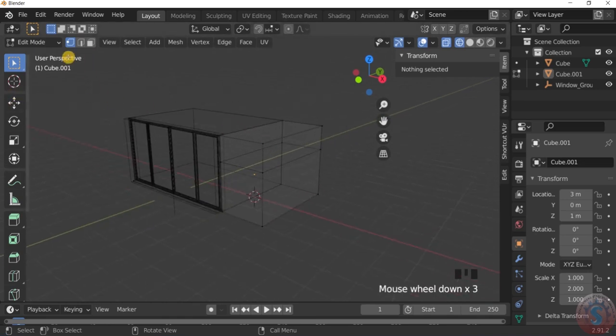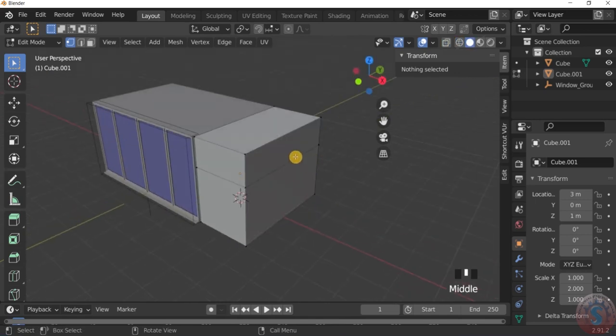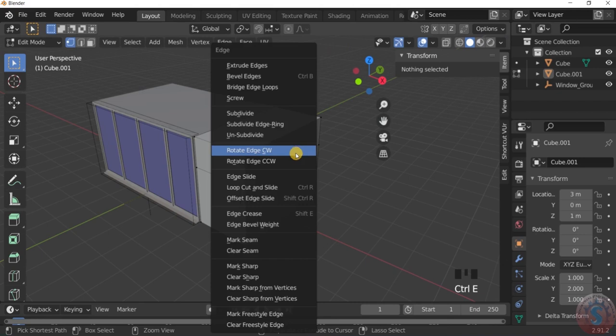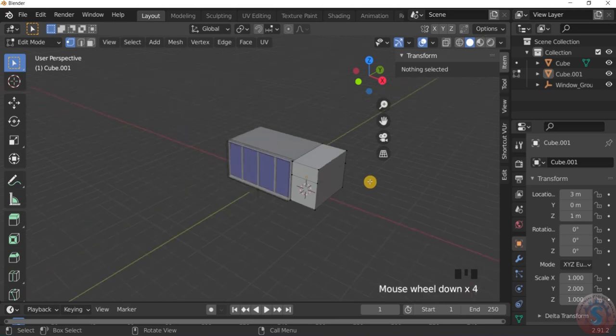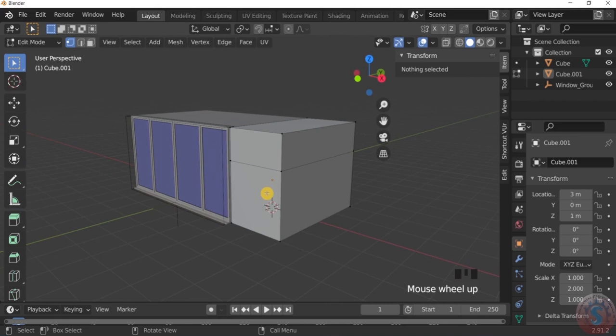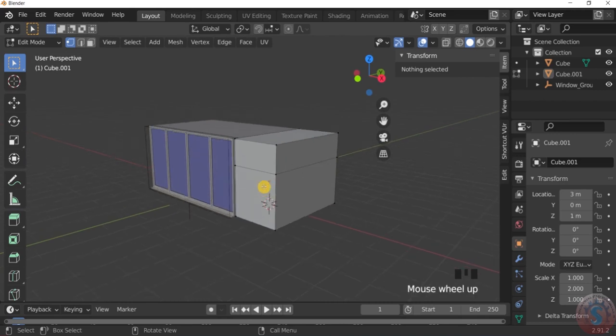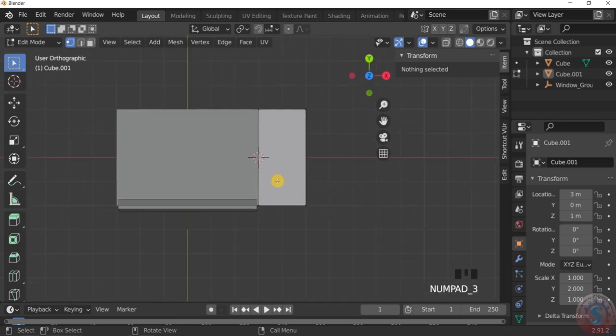You can observe I created this, and go into the edit mode and again Z, go into the solid. You can create this by using Control R also. By using the Control R key, you can give the loops. Now in this I don't want the loop. I can observe cross loops, and you can observe I created like this. Again I want to extrude this. For example, extrude this by pressing 3 or 1 key, by using the 7 key and changing the